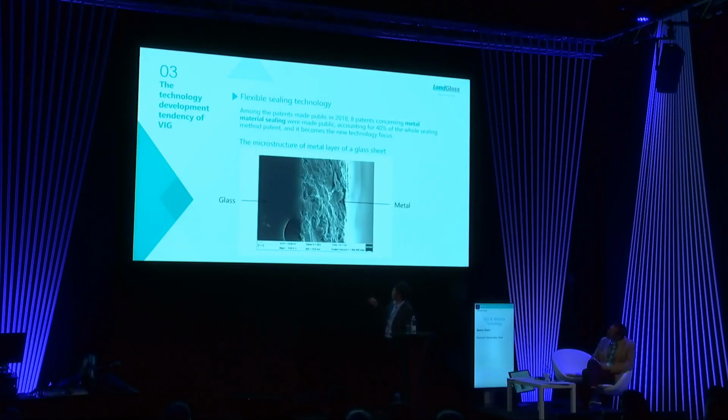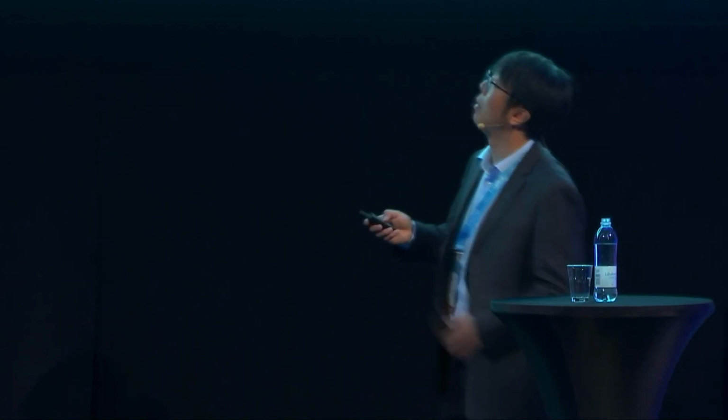You can see these pieces are joined by a soldering process, so the metal pieces and the glass pieces can join together very well. During deformation caused by temperature difference, there is low stress inside, so it can guarantee the vacuum of the VIG. So it gives you a super long life for the vacuum insulated glass.